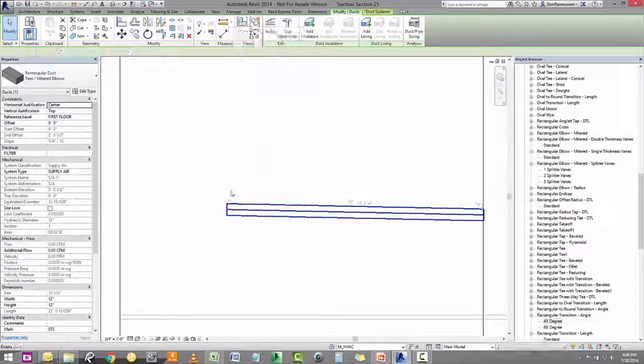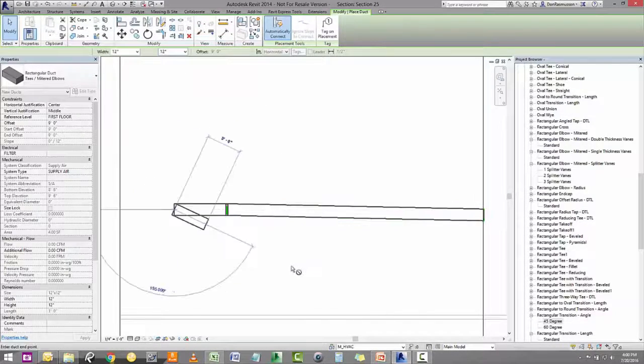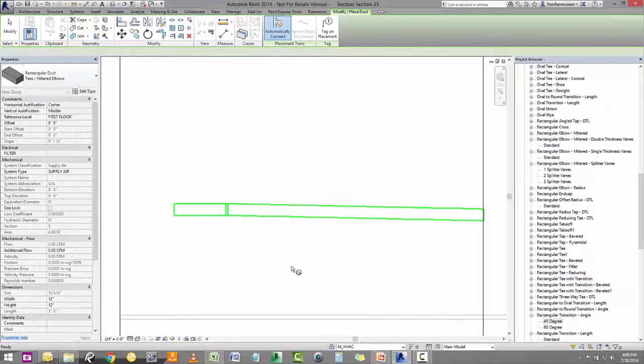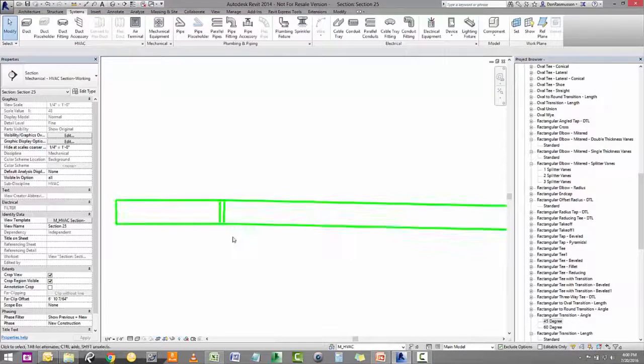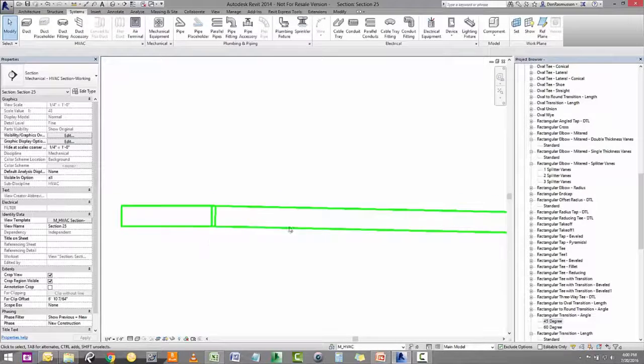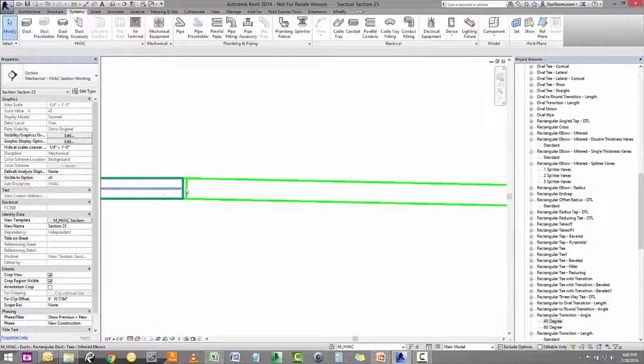We'll go add on to this piece of duct, and it does add just fine. Now we'll put these fittings in here. If you want to run quantification on the system, even though you know that this fitting wouldn't actually be in there, this would all be black welded duct. All this can be ripped out in a schedule and quantified, but then these have to be accounted for in that quantification. Obviously these wouldn't be fittings, that would be made up for in the joints for contractors, things like that.